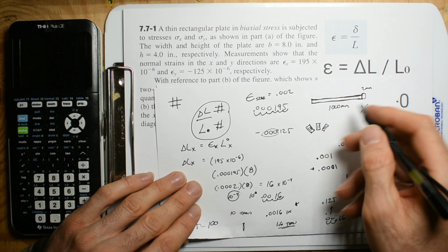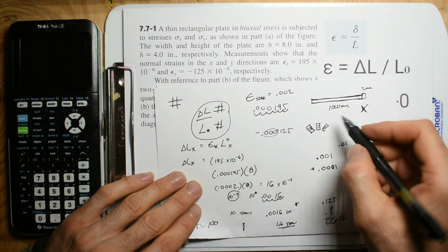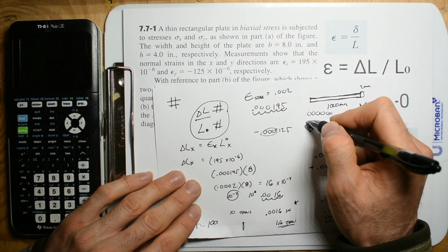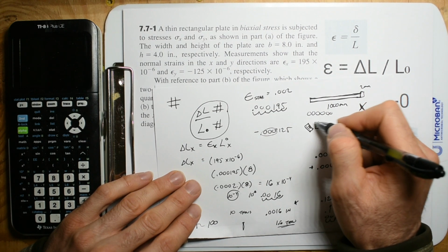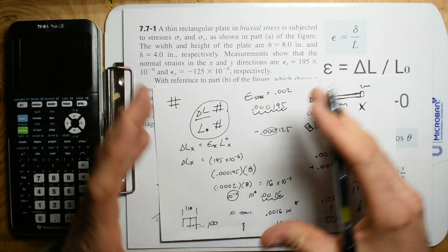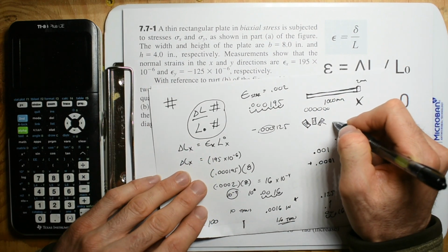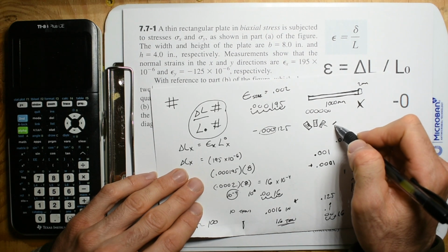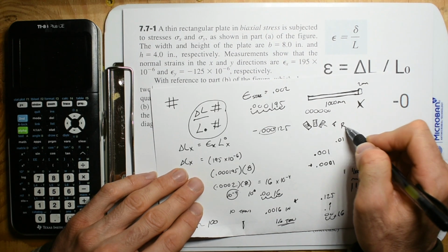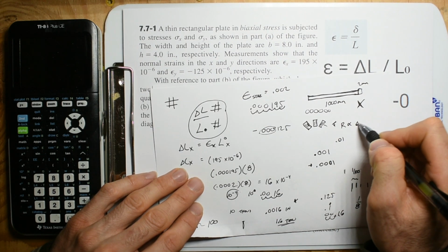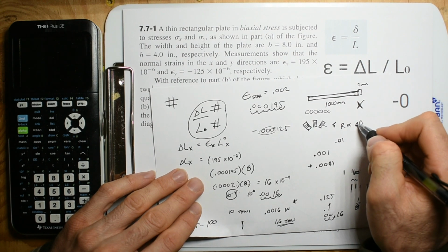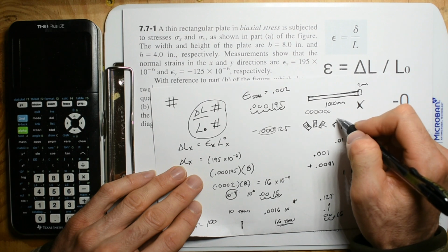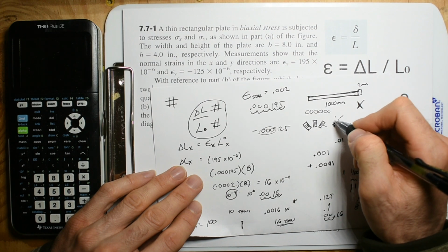But let's say your bridge is fairly lightweight and strong, and then you throw a bunch of cars on it. Now this thing is loaded, and when the bridge stretches in all directions, these wires are going to thin out, and the electrical current running through them can measure that resistance. The resistance in the wire is proportional to that change in diameter, and that change in diameter, due to Poisson's ratio, gives you the change in length in this direction. So it's kind of fascinating.